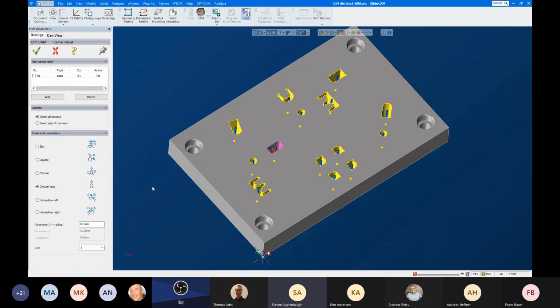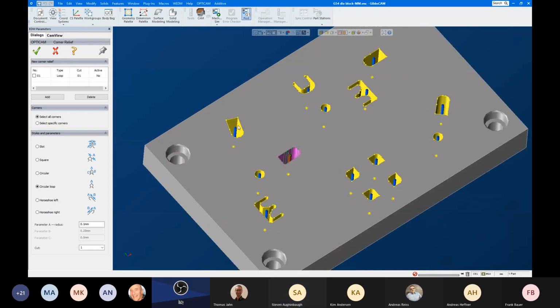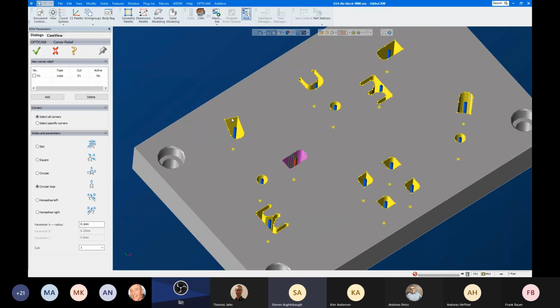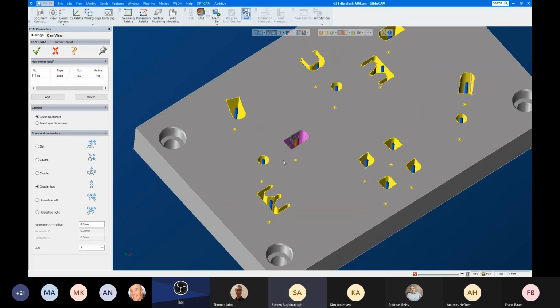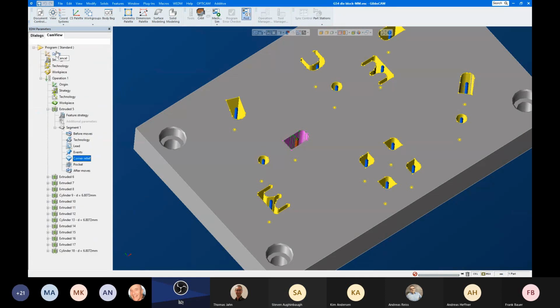And again, these become very specific to very specific types of parts you're trying to cut. On a part like this, I would group some of these together. If this was a punch block, I would not do a square corner here. I would do some kind of a circular corner, because otherwise it's gonna crack. I know that because I built dies for 16 years, so I know that this will crack here. So I would do some kind of undercuts. But the point is that we're giving you all the options.